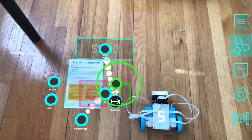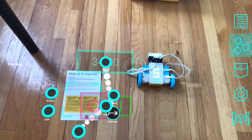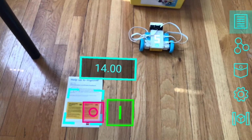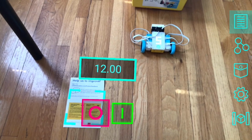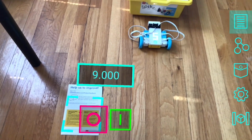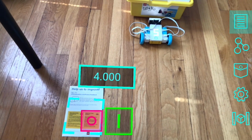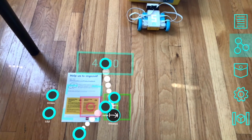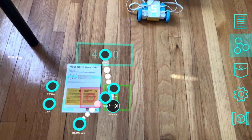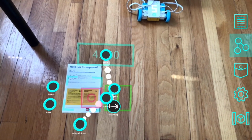So now if we go ahead and connect the distance to the motors, you can see the Spike Prime starts driving forwards and slows down as it approaches the box. And then once I flip the switch, it stopped the motors altogether. So if I let the motors go again, it drives very slowly towards the box. And I flip the switch again and the motors stop altogether. So we've actually made a proportional controller with just these 5 nodes right here.